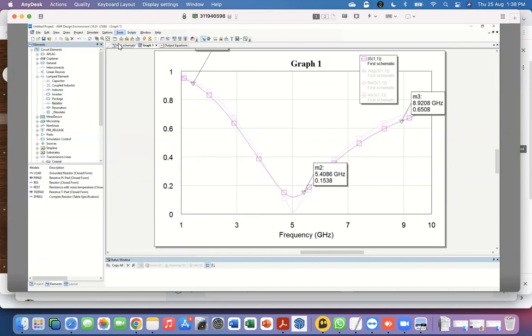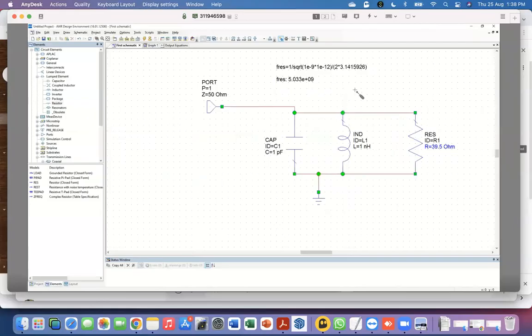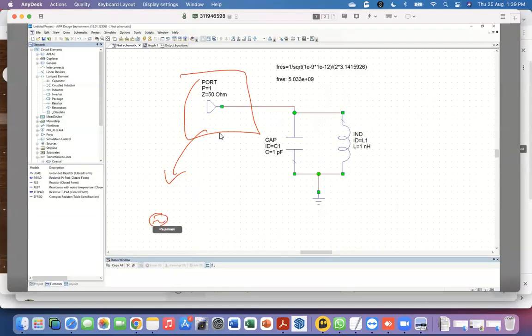Now to finish up with that caveat I was mentioning, let me get rid of this again. We said that because these elements cannot absorb energy or dissipate energy in the ideal sense, any real inductor or capacitor you make will always have some dissipative component. And we'll be looking at that later on how to model that. It's reflecting everything. But that somehow seems inconsistent with a picture that if I really think of this box as a voltage source with a resistor,